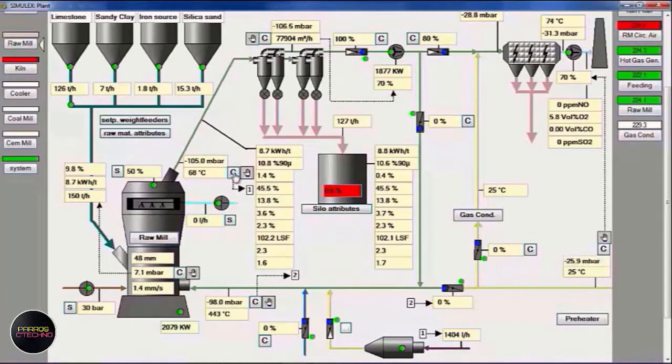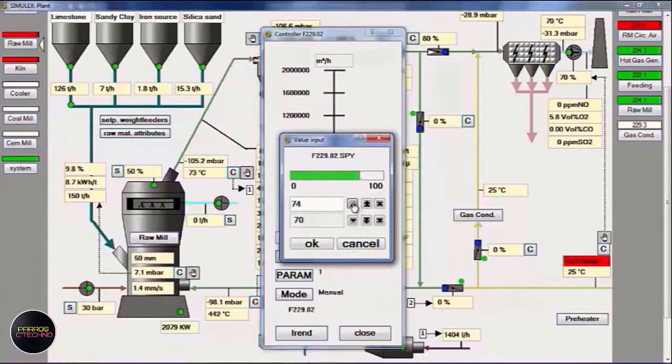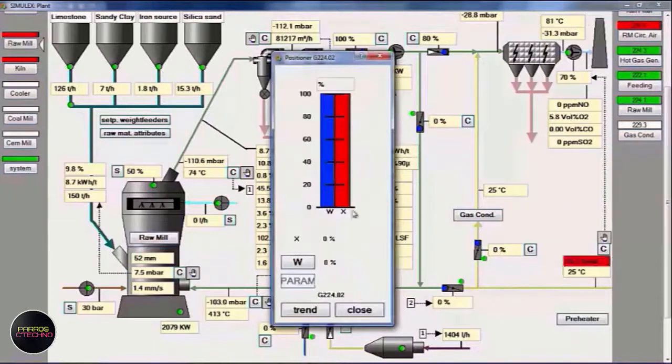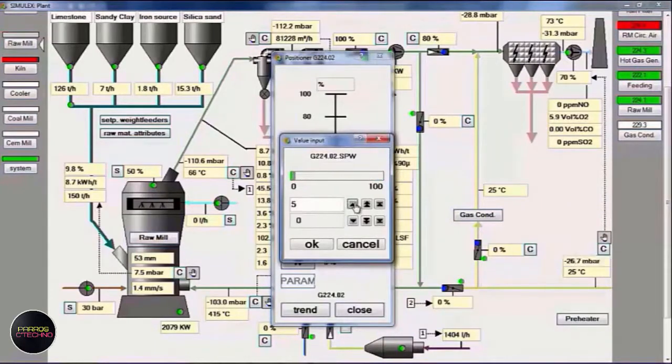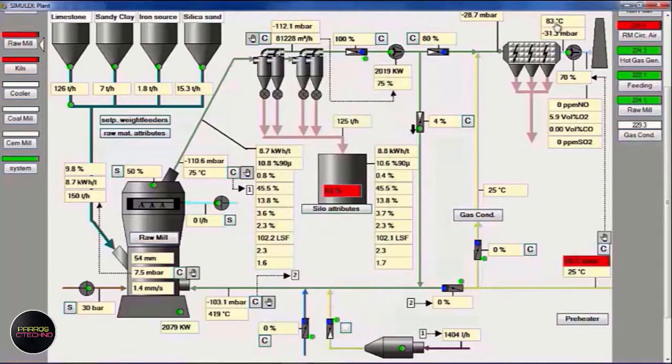We're back again to raise the temperature by adding suction. This is already 70%, which is quite high for a feeding of 150. Later, if the temperature at the inlet is high and the outlet can't go up, we have to open the circulation damper a little, only 5% to 10%. We observe not to let the temperature in the dust collector also rise, because if it is too high, the hot gas does not enter the mill but hot air enters the dust collector.